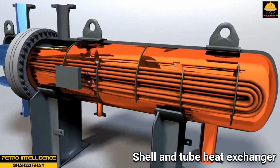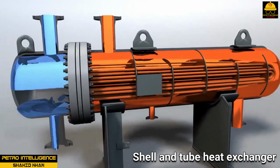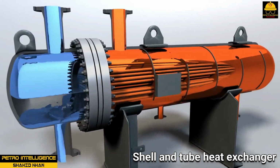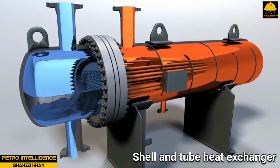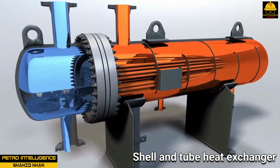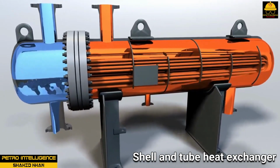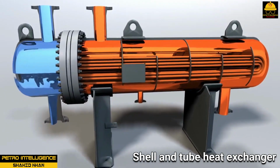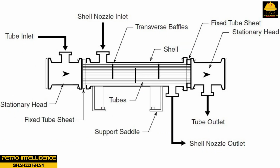As the tube side flow enters the exchanger or head, flow is directed into tubes that run parallel to each other. These tubes run through a shell that has a fluid passing through it. Heat energy is transferred through the tube wall into the cooler fluid. Heat transfer occurs primarily through conduction, first, and convection, second. This picture shows a fixed head, single-pass heat exchanger.